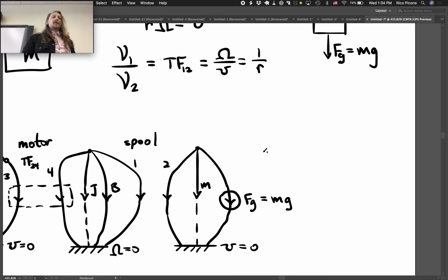And that's what gives us this connection to the inertial reference frame, the ground. But it's a sort of virtual connection, right? Because the mass isn't actually connected in a direct way to ground. It's just we're referencing its velocity to ground, which is why we do that dashed line. We treat it just like any other element. If you forget to dash the line, it's not a big deal. But we dash it just to remind ourselves that it's a sort of virtual connection.